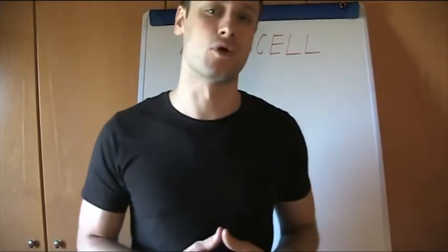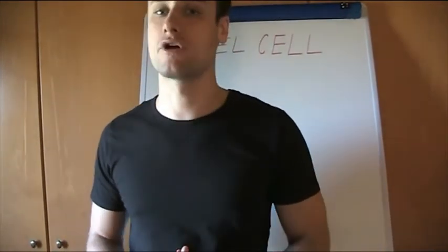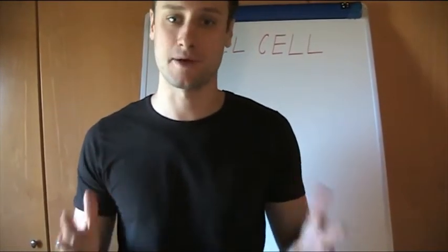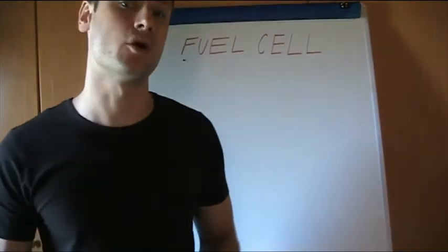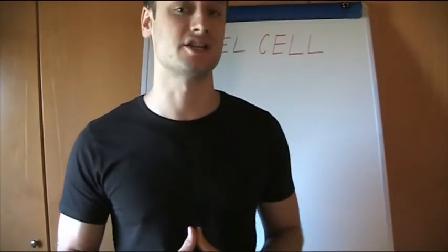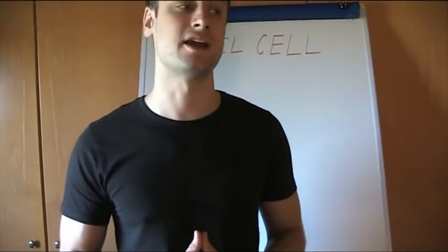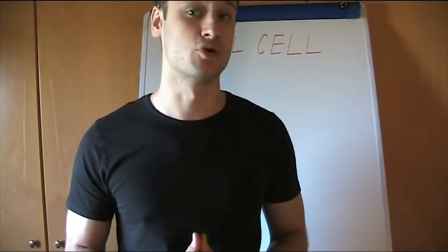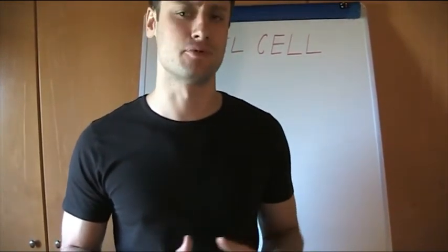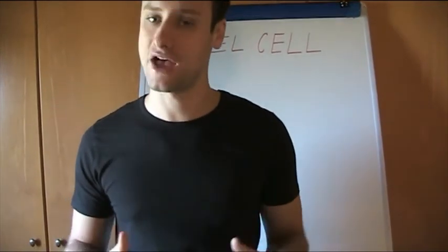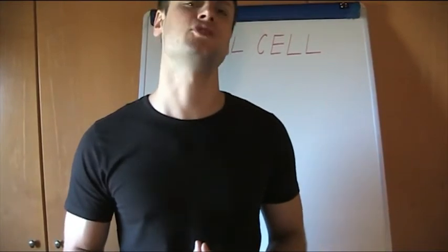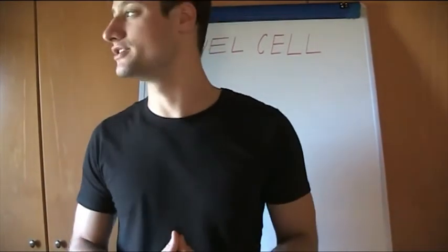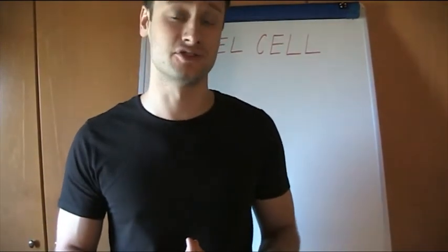The fuel cell working at high temperature. So now we are going to speak about high temperature fuel cell. But why high temperature? Because in this case the operating conditions require high temperature, for which we can avoid the system for water management, extremely important for instance in conventional fuel cell, as in the case of proton exchange, in which the amount of water should be tuned in order to avoid the drying of the membrane.